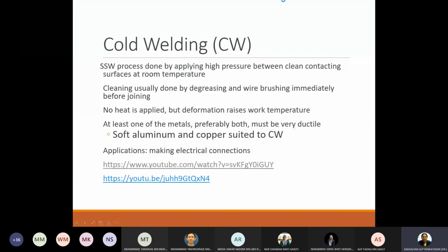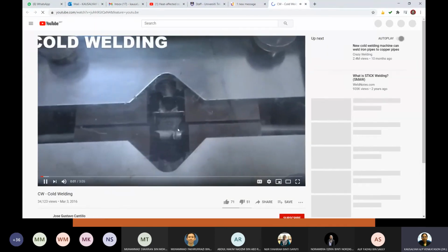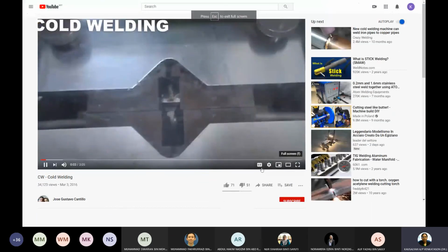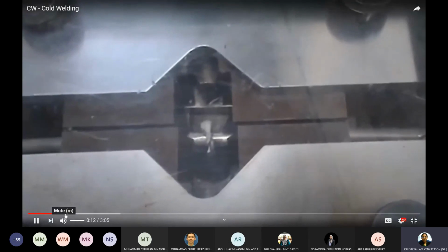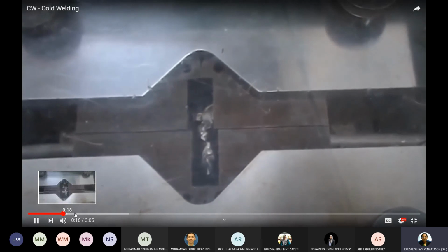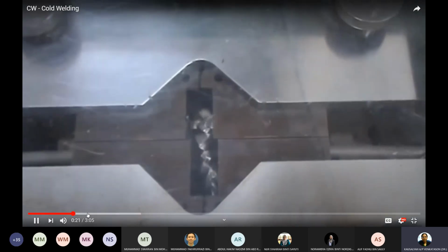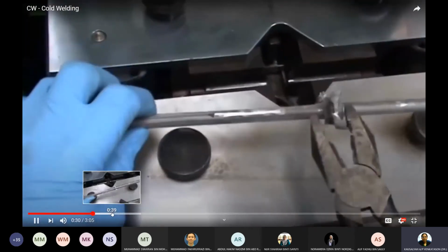So basically it allows the atomic bonding to take place to fuse. Cold or contact welding is a solid-state welding process in which joining takes place without fusion or heating at the interface of two parts to be welded. Unlike the fusion welding process, no liquid or molten phase is present in the joint. So it's basically like putting plasticine together, but it's just that this is metal.